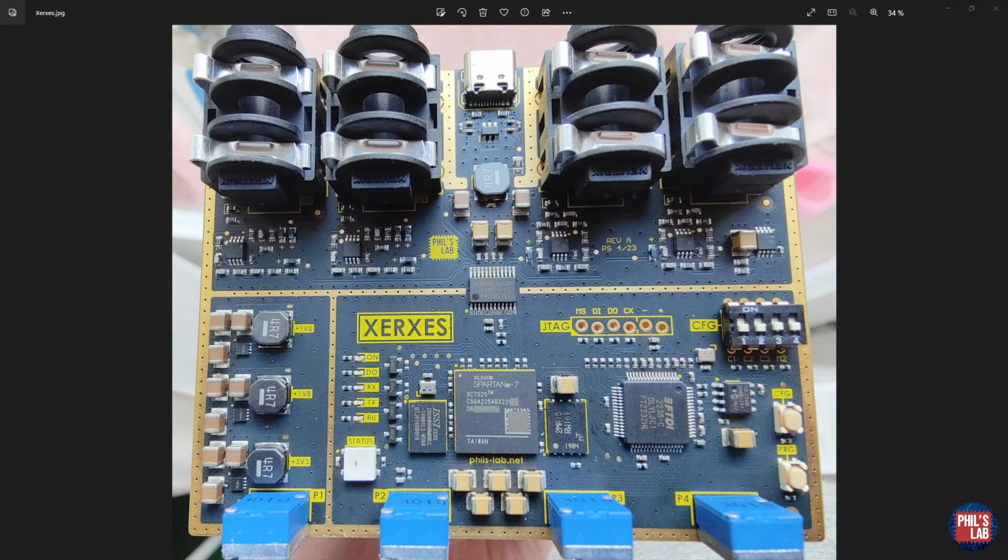Lastly, let me show you some practical real-world examples where I had to implement RC high-pass filters and how I sized them and chose them. For example, for this Xerxes PCB, also manufactured by PCBWay, which is effectively a mixed signal PCB with a Spartan 7 FPGA, some memory and control interfaces, as well as an analog section, which then feeds a codec, so an ADC and DAC, where I can do digital signal processing on the Spartan 7 FPGA. In the audio section, I've had to use several RC high-pass filters for various reasons.